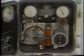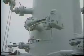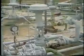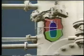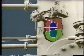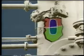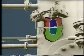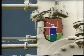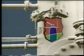It is also necessary to control the gas-liquid interface or the oil-water interface in the separator. This is done by means of a level controller and liquid dump valve. The most common form of level controller is a simple float, although electronic sensing devices can also be used. If the level begins to rise, the controller signals the liquid dump valve to open and allow liquid to leave the vessel. If the level in the vessel begins to fall, the controller signals the liquid dump valve to close and decrease the flow of liquid from the vessel.